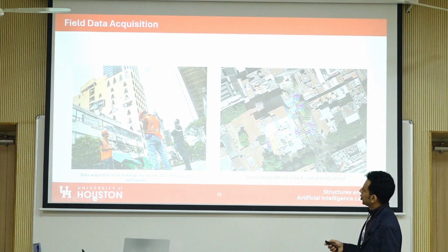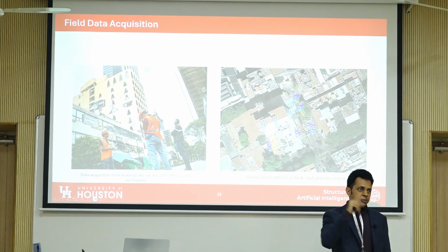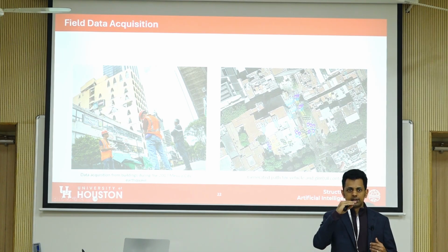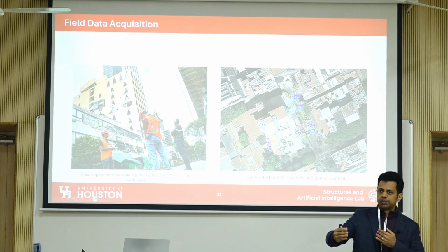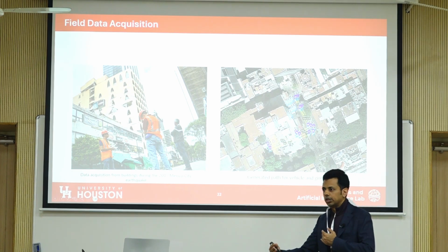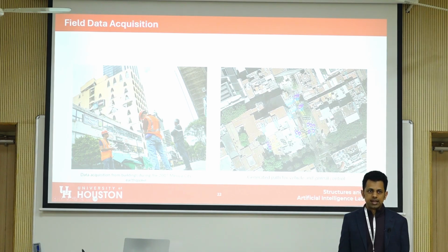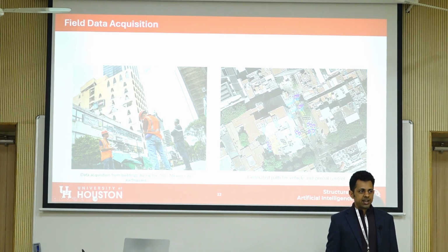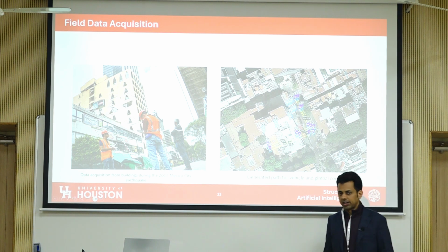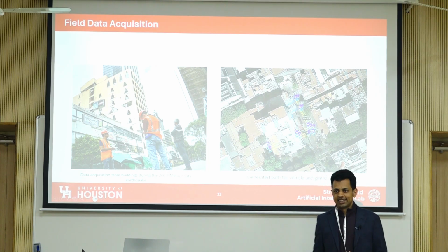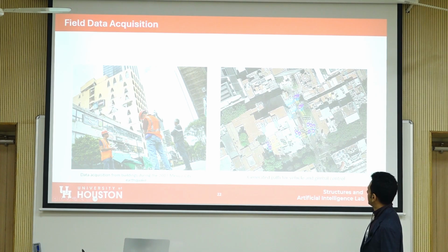You need to make sure you're covering the structure, right? So when you plan how many paths you're taking, you need to calculate, based on how far you are from the structure, what the height difference is between the successive paths. Also, there's usually GPS error, so you need to do some tests to see what the GPS error is, and calculate whether there's a chance that you might hit an obstacle. All of that needs to be taken into account, and then you can deploy that.